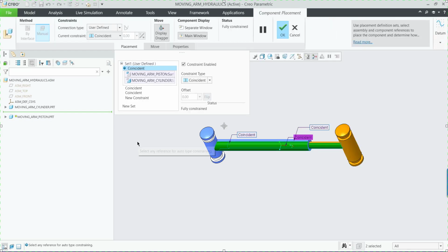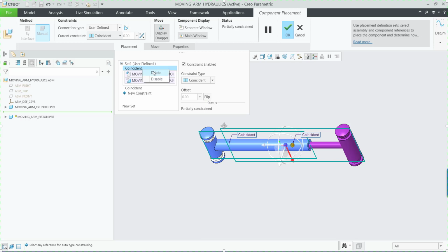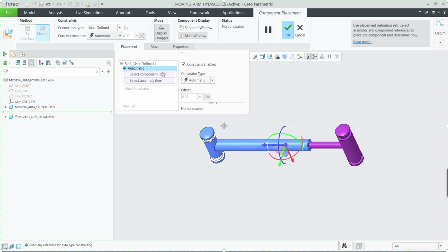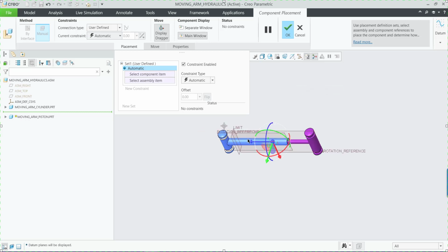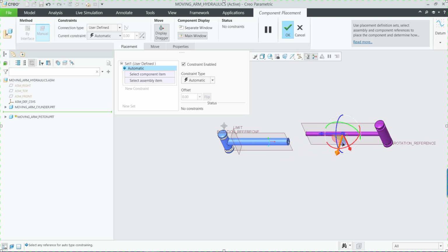Here, instead of releasing the degree of freedom and then trying to convert the constraints to connections, I will just delete all the existing constraints which are available. Then let me enable the plain display, and I will just take it out from this hole somewhere here.